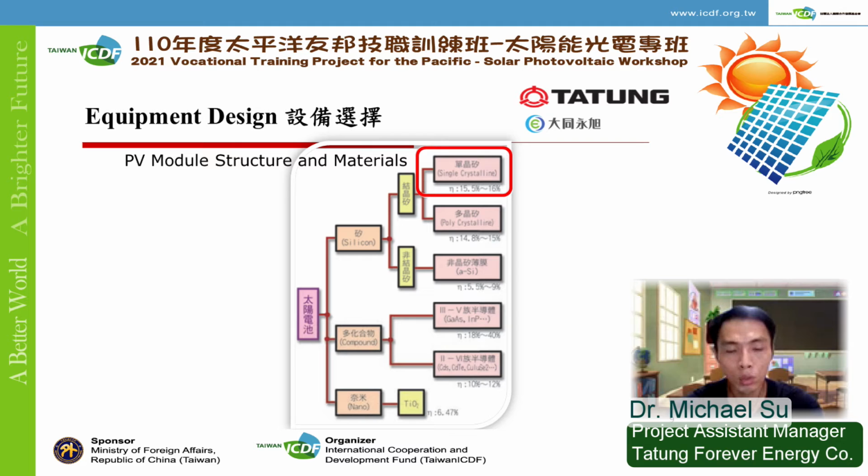As mentioned previously, besides the monosilicon and polysilicon, which are silicon materials, there are also non-silicon materials for the solar cells, such as the amorphous silicon solar cells. In the past, there was even the gallium arsenide indium phosphide semiconductor and the CdS or CdTe semiconductor, and also some nano level ones too. However, the most popular ones that are used nowadays are the monocrystalline types. They are still the majority.